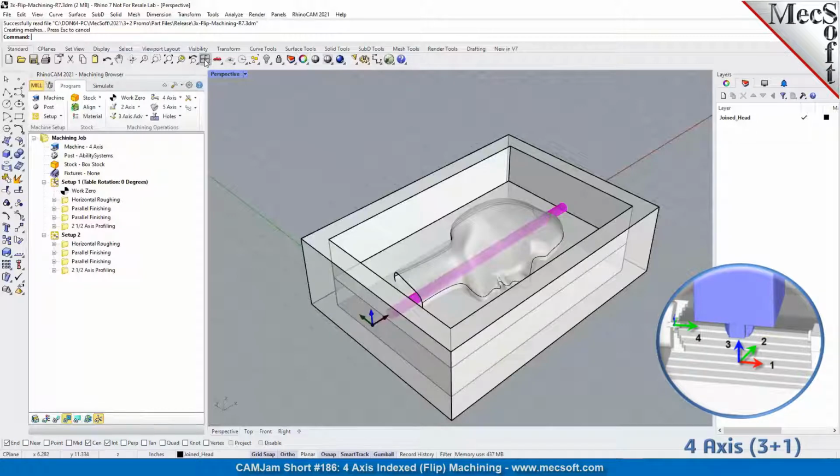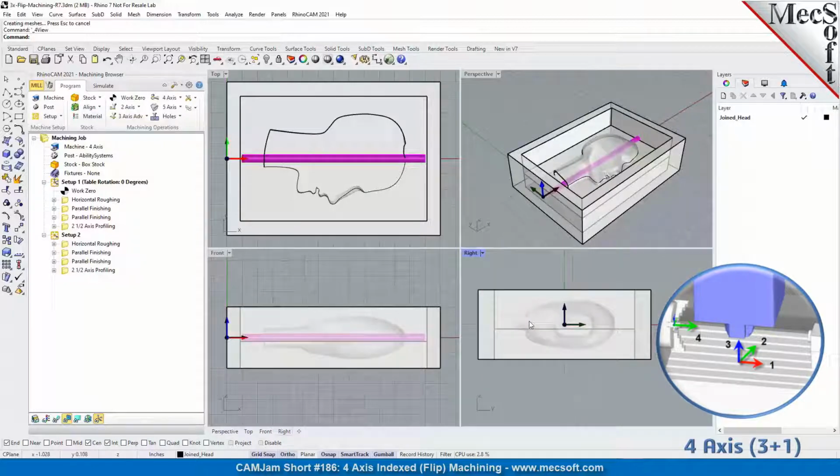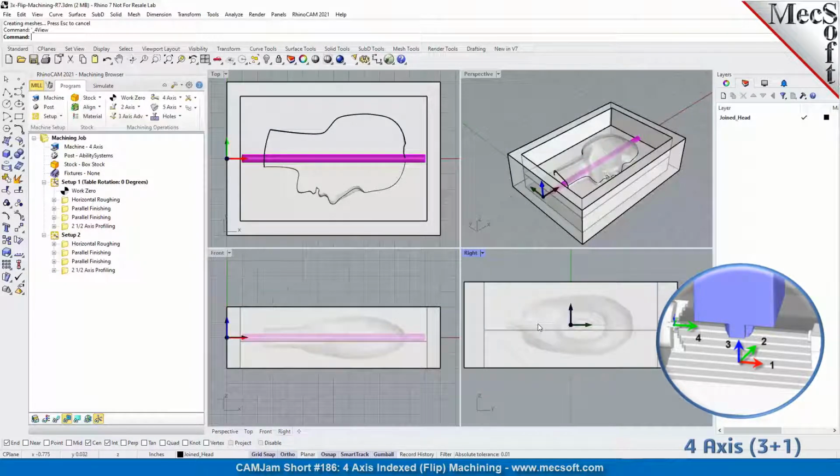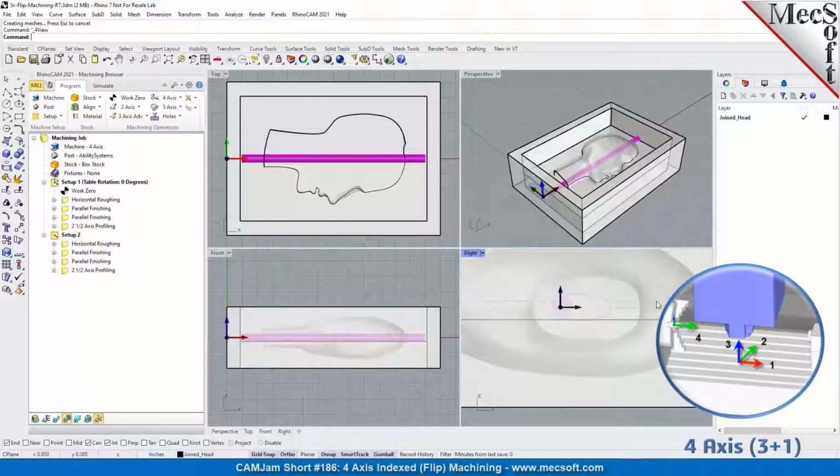Was that something we program in our system, or is that something that needs to be done in the CAD system? So yeah, that's something that you need to add. Well, you can do it both ways. In your first operation, in your roughing and in your finishing, you can control your Z depths, but it's a lot easier to just put the catch plane in there. You see we got it at the bottom of our cylinder. So the tool paths are going to roll over the part down onto the catch plane. It's a lot easier if you just put the surface in there and the program recognizes it automatically and accommodates for it.